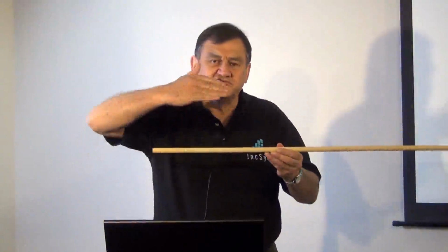So basically, your reactive sources are two types that can be dynamic or static. By dynamic, we mean that reactive source will respond pretty much instantly under its own control to accommodate changes in your system. Primarily, we're looking at transmission line outages or losing a generator. When you have a transmission line outage, what happens is the load on that transmission line transfers to other transmission lines. They become more heavily loaded and they draw more megavars.